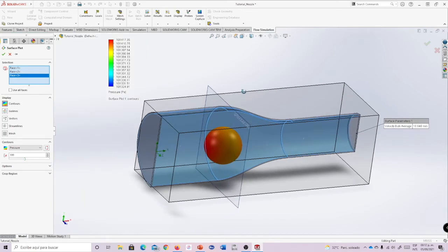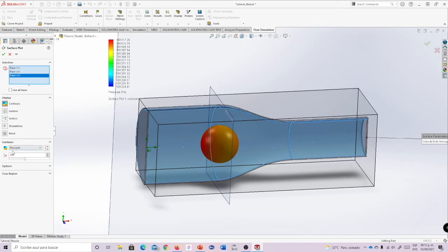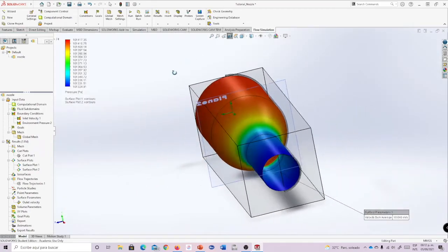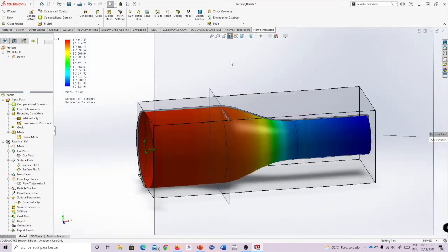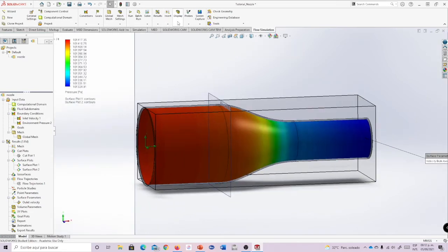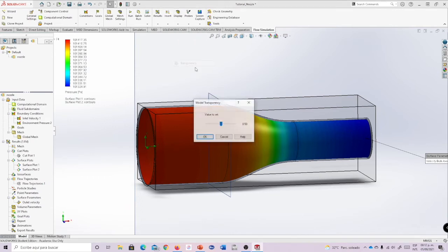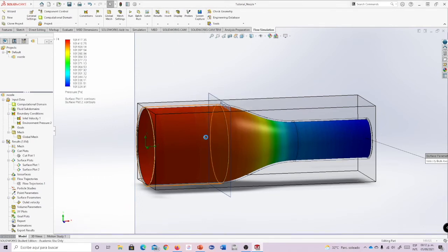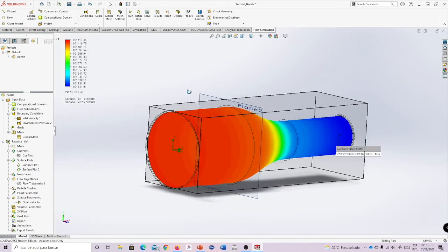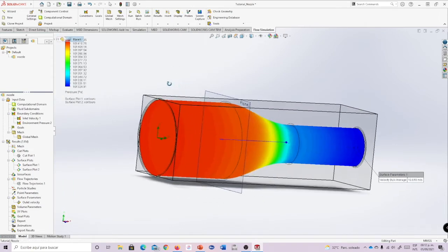And on those surfaces, the inner surfaces, we want to draw contours for the pressure. I'm gonna leave this value 100, and I'm gonna click OK. There you have. I'm gonna deactivate the section view, and I'm gonna set the transparency again to 100. Maybe the lighting can also be changed. Okay, there you have.